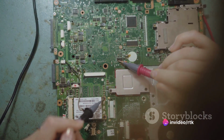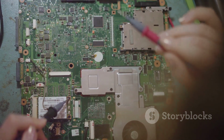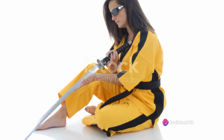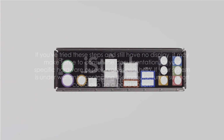Test with minimum hardware. Disconnect all unnecessary external devices and try booting with the minimum necessary hardware, such as the CPU, one stick of RAM, and the GPU if necessary. Inspect for physical damage. Examine the motherboard and components for any signs of physical damage, such as burnt areas or damaged connectors.